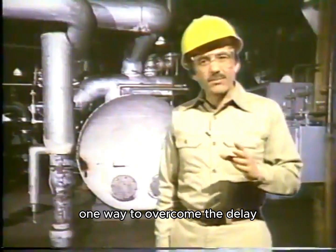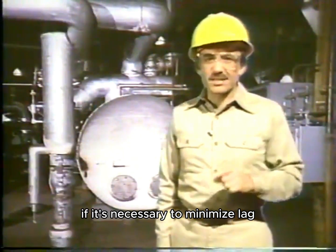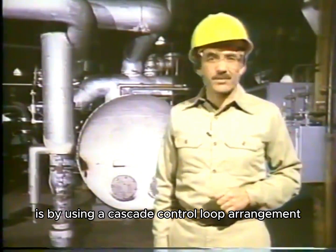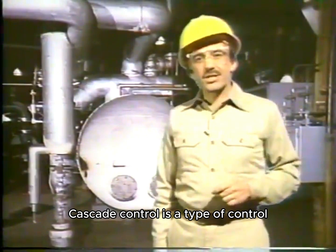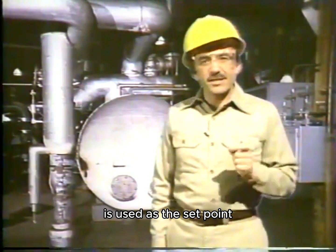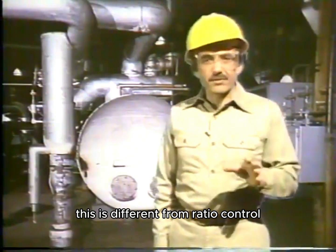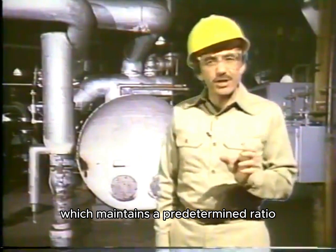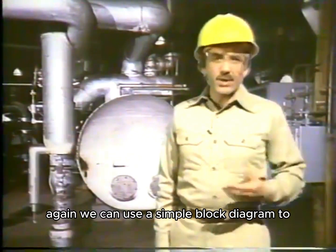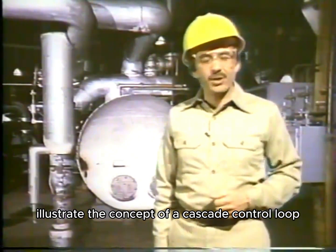Now, one way to overcome the delay characteristics of this process, if it's necessary to minimize lag, is by using a cascade control loop arrangement. Cascade control is a type of control in which the output of one controller is used as the set point to regulate a second controller. Now, this is different from ratio control, which maintains a predetermined ratio of one variable to another. Again, we can use a simple block diagram to illustrate the concept of a cascade control loop.